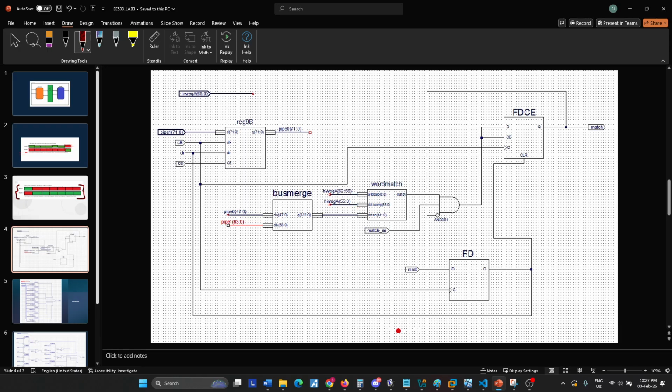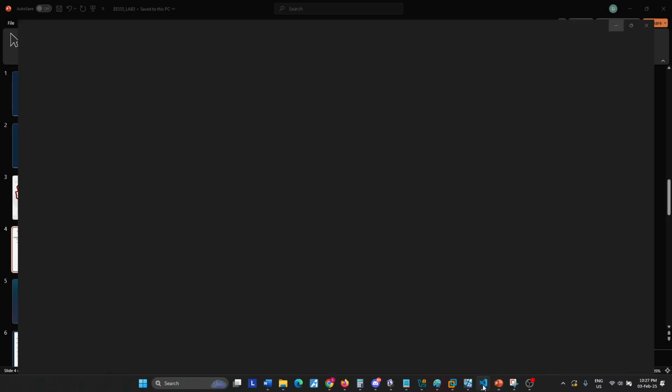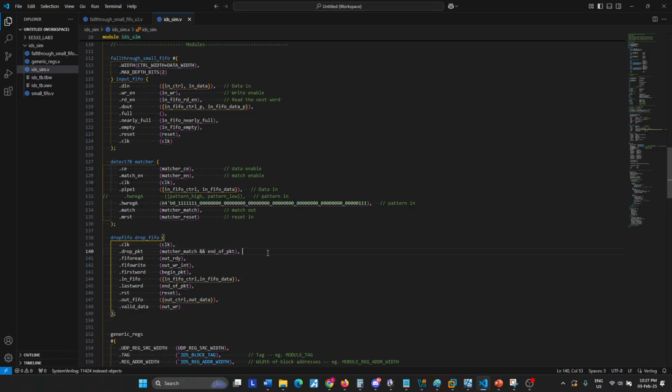The reason we do this is because in the code we are giving this particular pattern to hardware register A. You see these 7 bytes, the lower 7 bytes, are essentially the pattern to be matched, and the upper 7 bytes are the mask, also called A mask here. So now we need to understand what the A mask actually does.